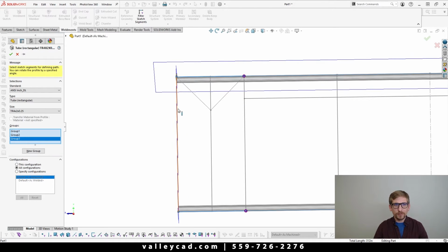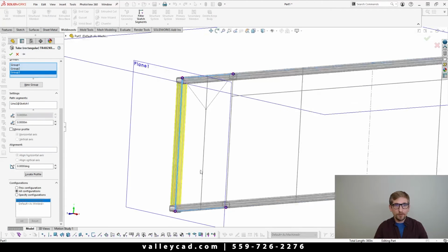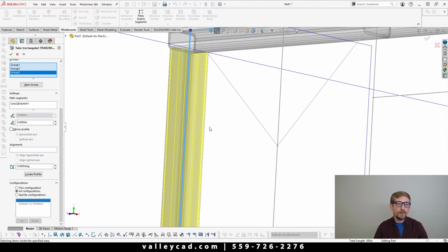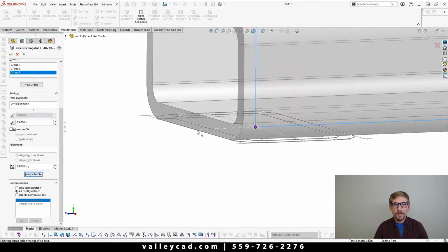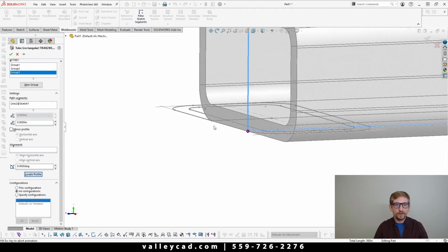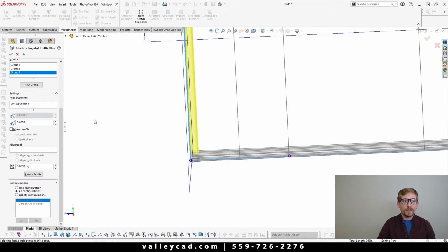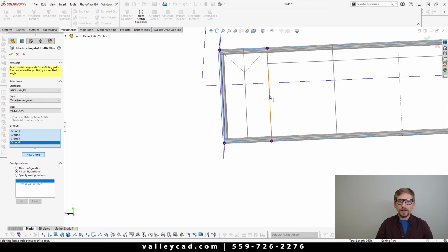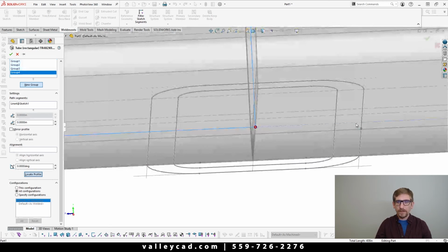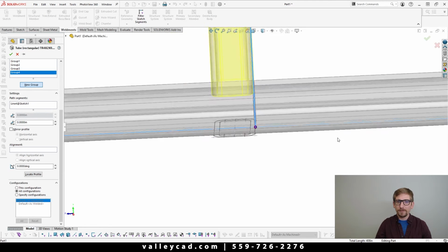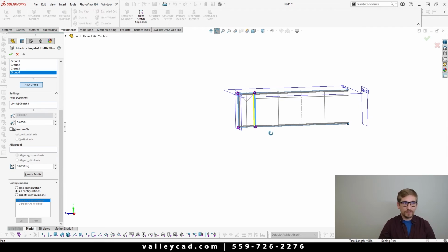With our new group, we'll simply click here, and on this, we're gonna have to say locate profile again, because maybe I wanna make it so that it's coming to the inside of that. So locate profile, we're gonna click on, not that point there, try it again, locate profile, and click on that point. Then from there, we'll say new group again, and simply come in and click here. And then from there, we'll say locate profile again, and we're gonna click on to that point there. So now we're making everything going to the inside of our sketch geometry still.